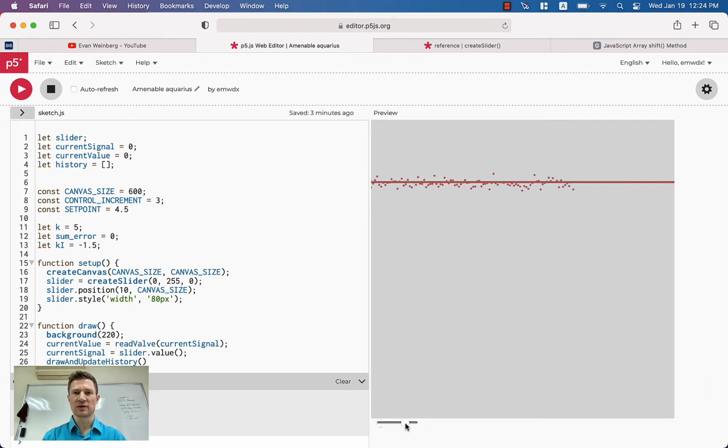This approach we might consider to be a candidate for on-off control. But the way we implement it in code is different from what we might do for any of the other tasks. That's specifically because we don't have a way of directly setting the output to be fully on or fully off in this control problem. Take this and slide it all the way to the bottom, and that's obviously too much. Turn it completely off, and that's obviously too little. And we want to do better than those two extremes.